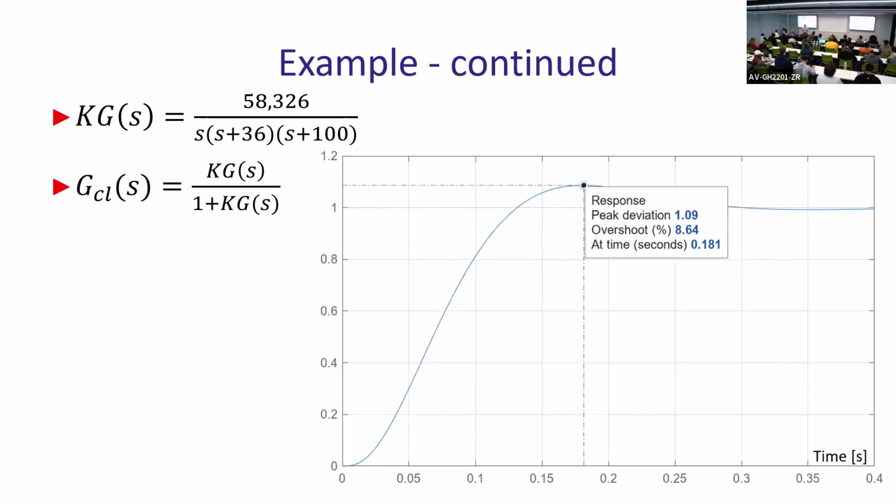So you don't want it to be higher than 9.5. Yeah, 9.5 is your higher boundary. So you typically want minimal settling time, minimal rise time or peak time, and you want minimal overshoot, and you want appropriate bandwidths, things of that kind. This is what you typically want from control systems. Right? Any other questions?